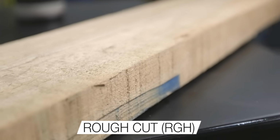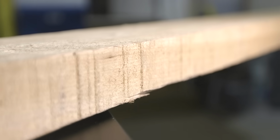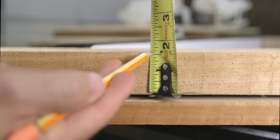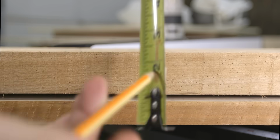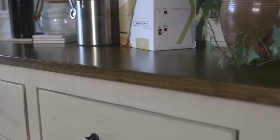Rough cut lumber, RGH, is lumber that is, well, rough, and in most cases you can still see the saw marks from the mill. Rough lumber is sold by the 1/4 inch in its thickness, and its width can vary just depending on what's available in your area. For example, a 4/4 board measures around 1 inch thick, a 6/4 1.5 inches, an 8/4 2 inches, and 12/4 3 inches. Lumber like this can be used for rustic projects, or it can be sized down by using a jointer and a planer for furniture.